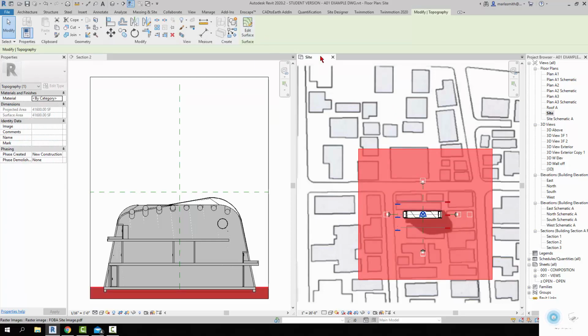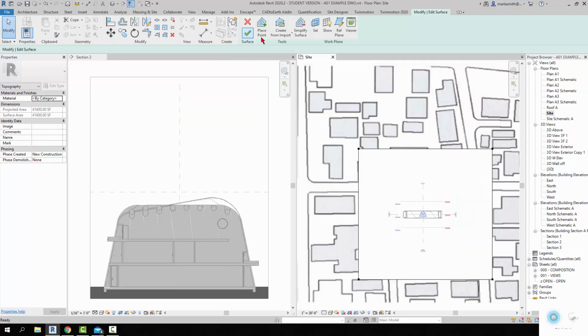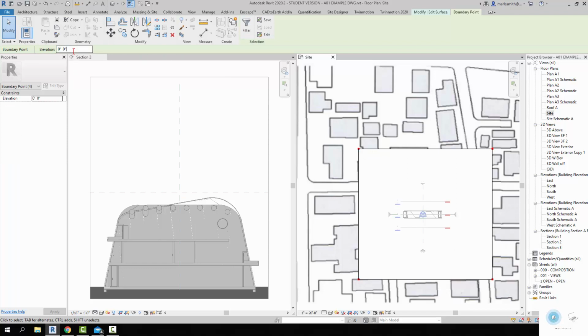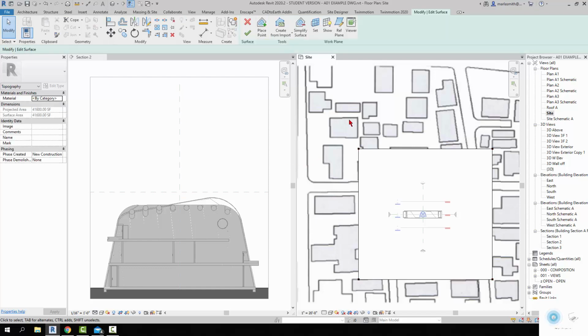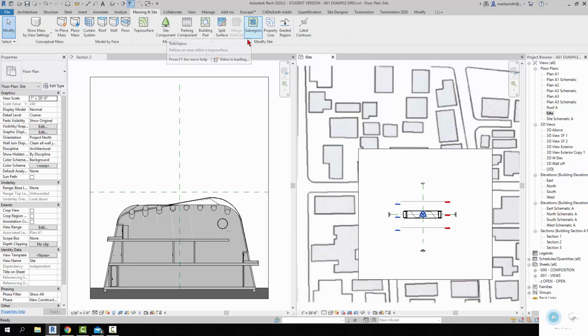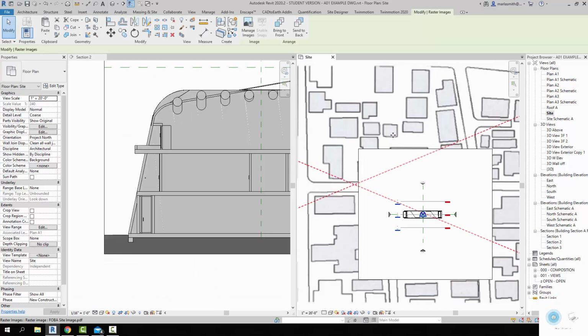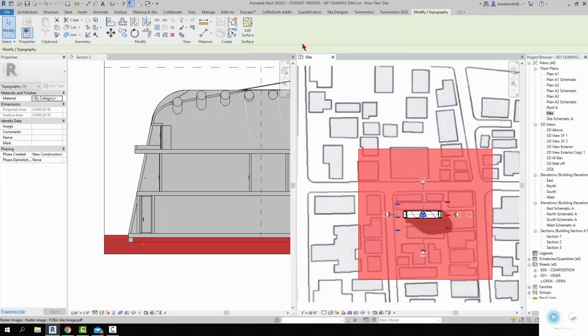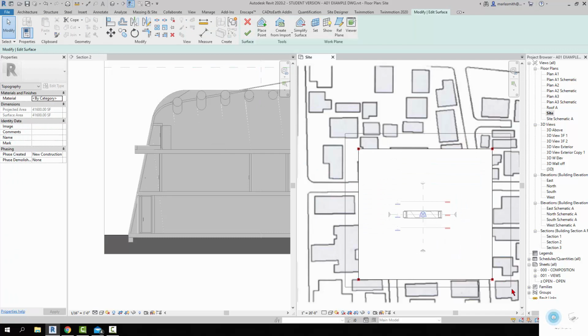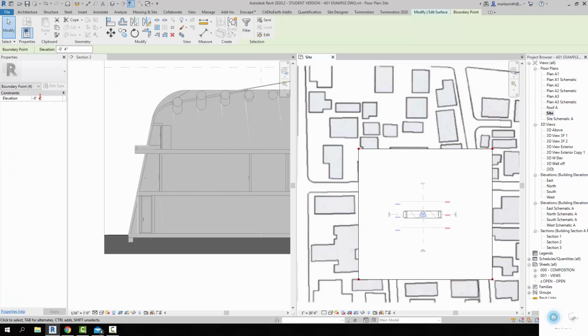And what I want to do is, it doesn't show the points. I actually have to go to Edit Surface, and that takes me into the sketch mode, and then it isolates this, and I can window around and pick those points, and I'm just going to lower the elevation to -4 inches, right? And then if I hit check, you'll see that thing has dropped 4 inches. Maybe we'll do it even a little more. Maybe we'll just do 6. Right, -6 inches.